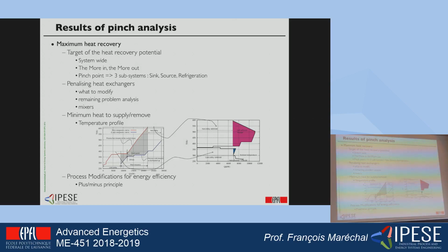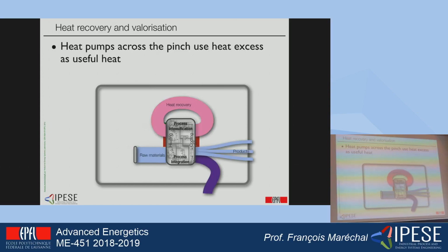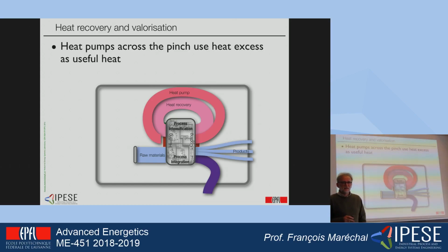which defines in fact the temperature at which the heat has to be supplied or the heat that has to be removed out of the system, which then allows us to identify the heat recovery plus the possibility of integrating heat pumps, which is always taking the heat that is below the pinch and sending it back above the pinch.